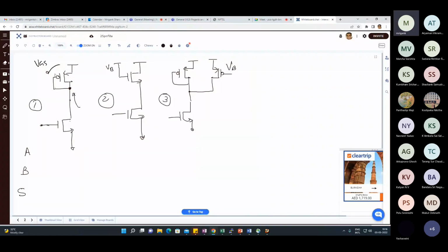Conceptually, without doing the small signal analysis, you can understand that the ro effect is going to be much smaller as compared to the VGS effect, because VGS has a much stronger dependency. Since you are changing the VGS directly, if the output voltage level is changing, the VSG of the PMOS itself is changing.